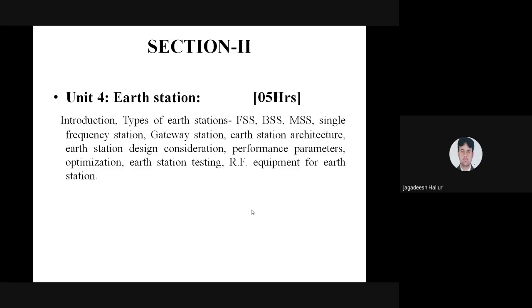If there is a variation in the weather conditions, once the rain has started, you will get a message that the signal is lost due to weather condition. That is because you have integrated the broadcast satellite service. If there is a problem in the weather conditions, the satellite is unable to give the signal to your particular antenna. If the weather is clear, then you will get a clear picture on your television. That is broadcast satellite service.